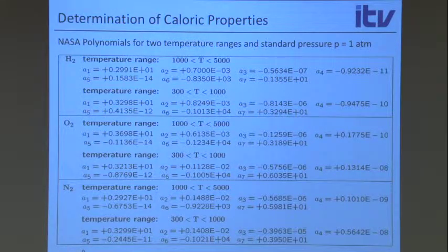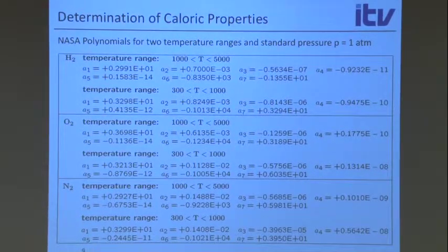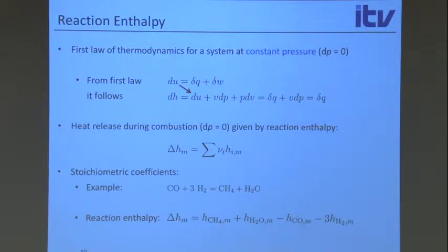Okay, so even if you have a numerical code that, while finding a convergent solution, goes to temperatures above 5000 or outside of this range, maybe it's not 5000, maybe it's lower, then the values might be garbage, because polynomials do crazy stuff if you leave the range for which they're fitted. Same for the lower temperature. If you go below 300 Kelvin, you can also get crazy stuff. Anyway, this is how these look like, and that's how we determine these.